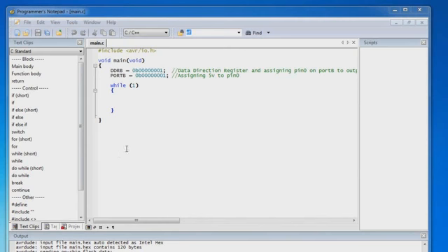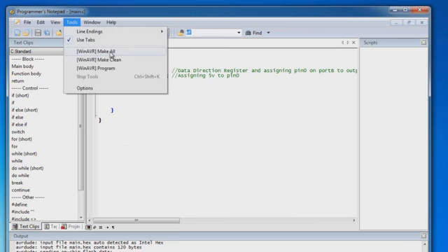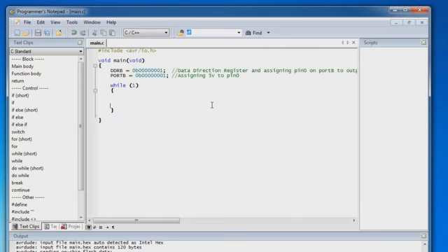Everything with this program will be a lot easier now. We did a lot of steps that we really don't need to do over and over again, like creating the make file. Right now we can essentially modify our program, and all we'll have to do is go to Tools, Make All, and then Tools again and Program, and those changes will be made automatically, and it will successfully program it as long as we have no errors in the code.